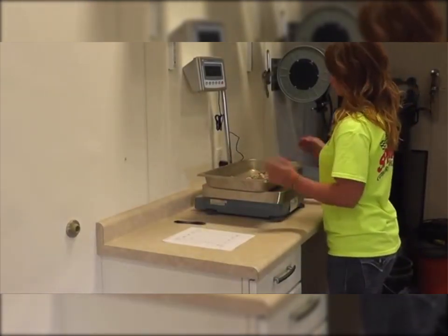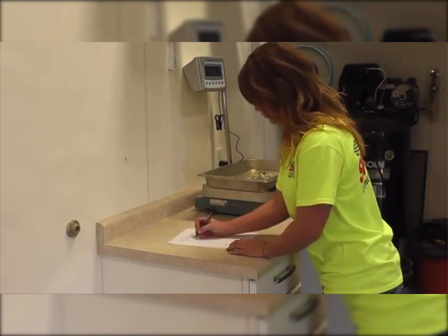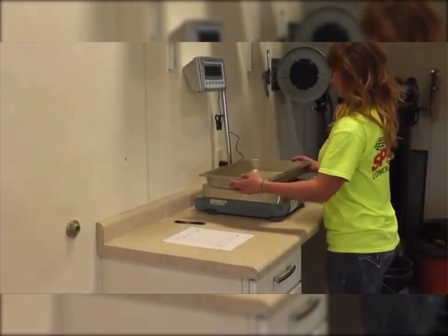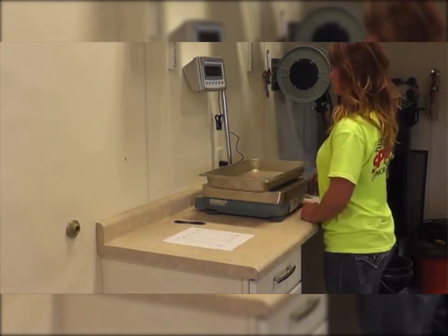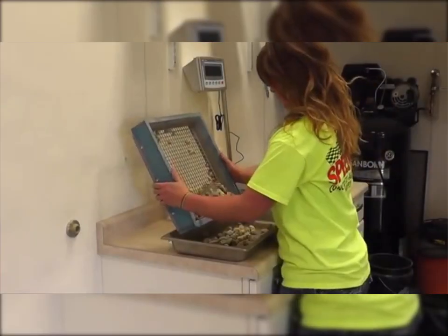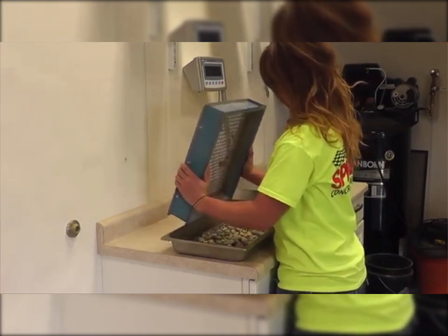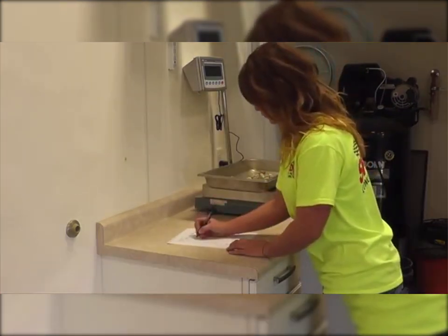Once the material is shaken for the appropriate amount of time, the material on each sieve and the pan is weighed and recorded. Before weighing the material, the weigh pan should be placed on the scale and the tare button should be pressed to a 0 reading or tare weight. Next, the material retained on each sieve and in the pan is weighed individually and each weight is recorded on the gradation form.